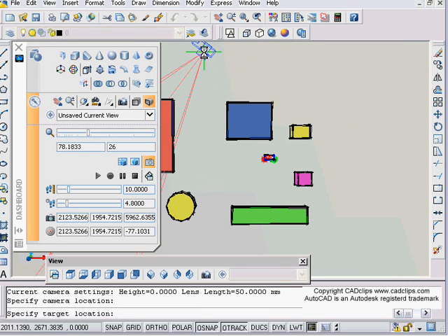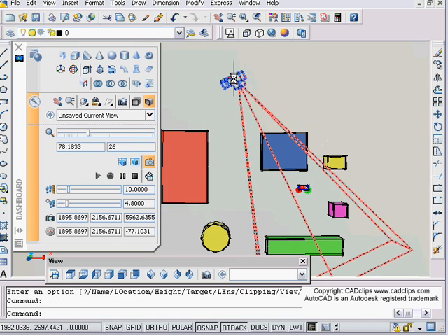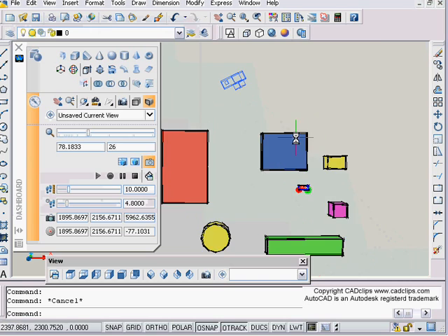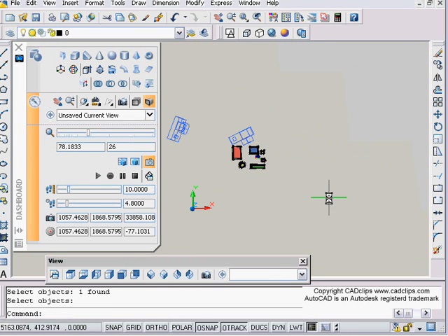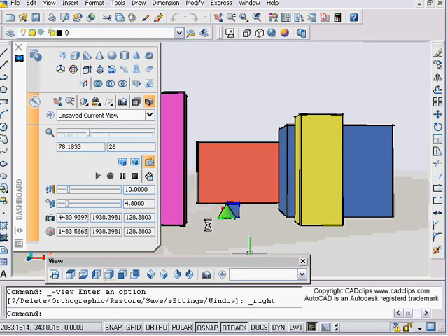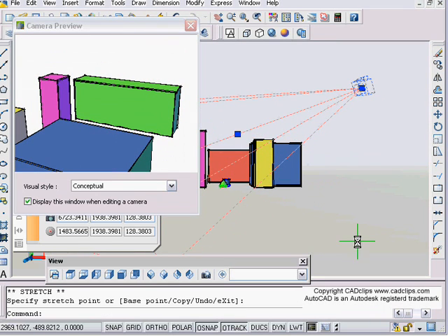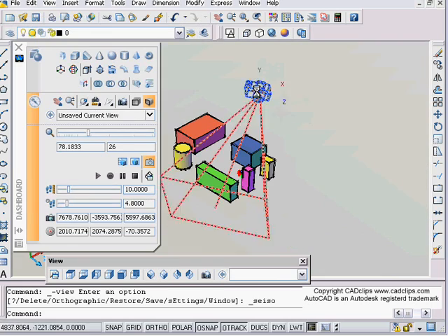Pretty straightforward. Pick the camera tool, pick a point, place it, and then have a look maybe at the help menu and set some more options. Basically, I just place it, and then after you set, notice your Z, change your Zs, etc. You could also go in here and move the camera just by going into, for instance, let's go to my right hand side view, okay, and I can grab that camera, and I can also move that camera up just by doing that, going into that view.